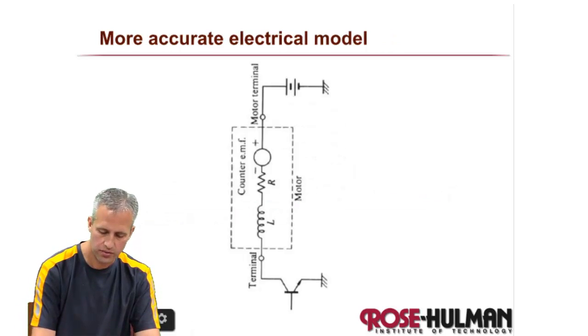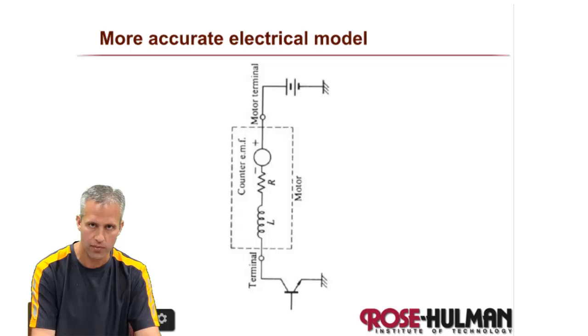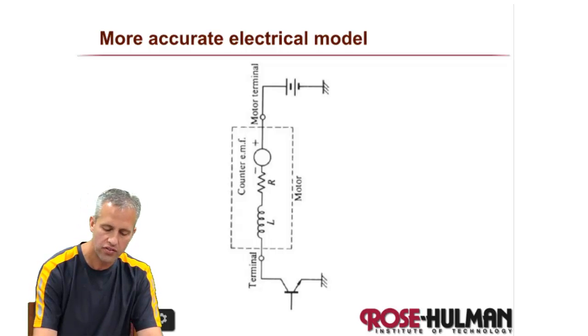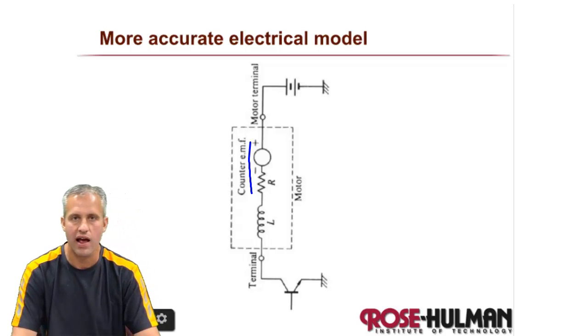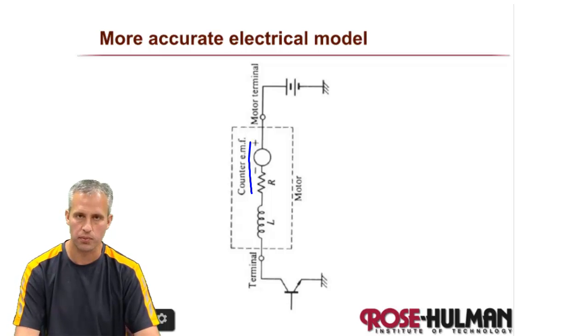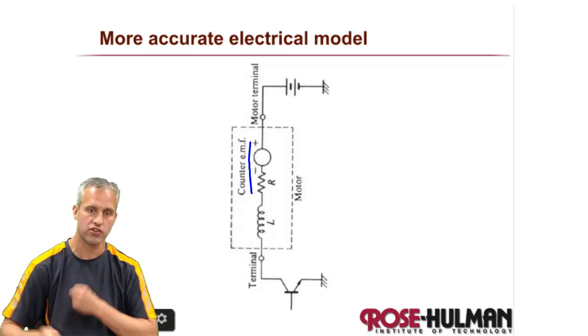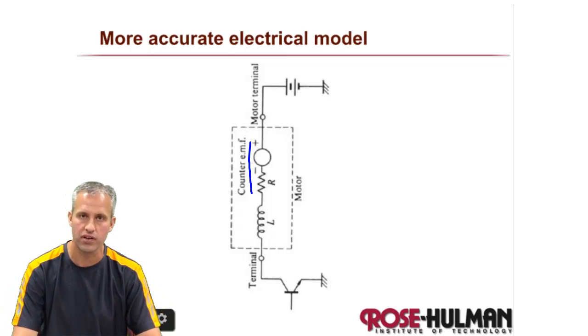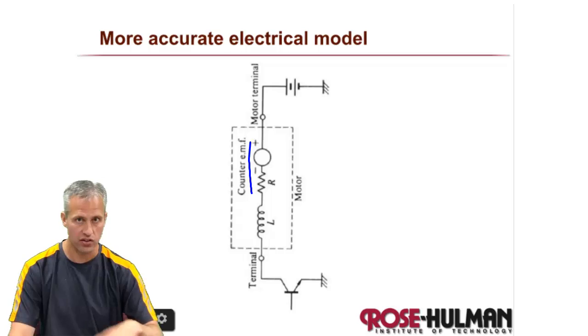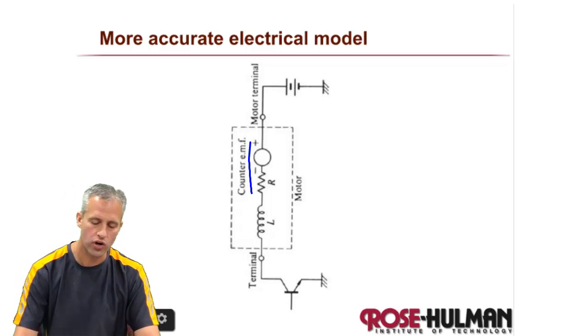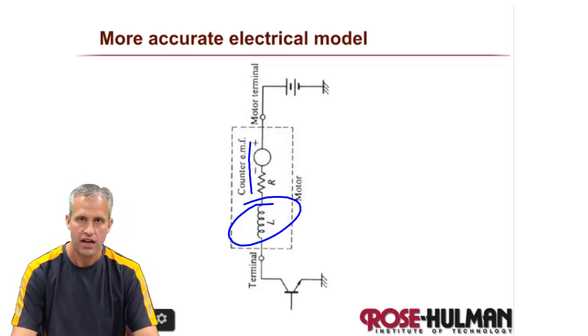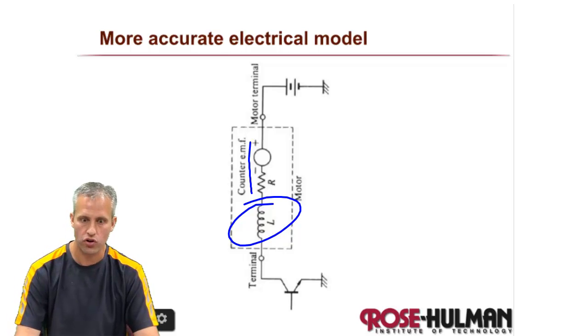So that's in the system. A real motor always has some inductance, and there's also a counter EMF. I'm not as worried about that today. That's what explains how generators work: if you drive the shaft, with gas power or by turning it with your hands, it creates a voltage. The main thing I'm worried about today is this inductor and how we handle what's called inductive kick.